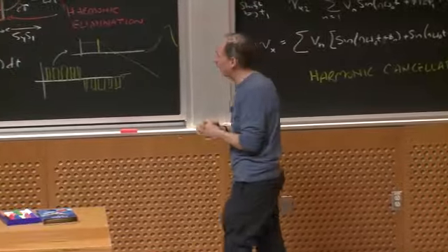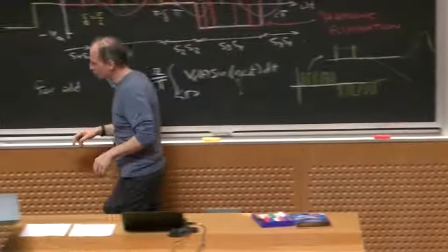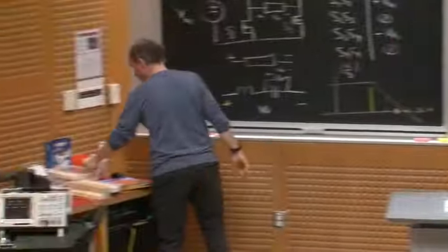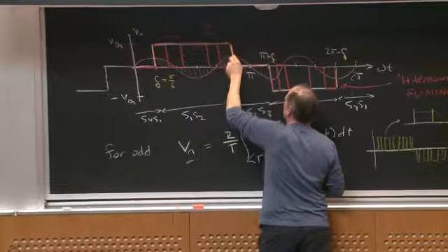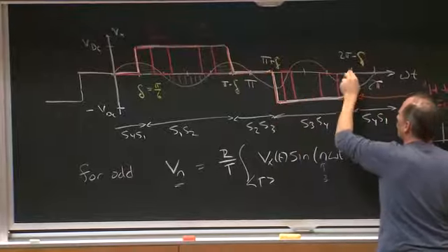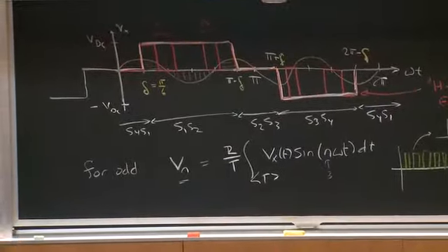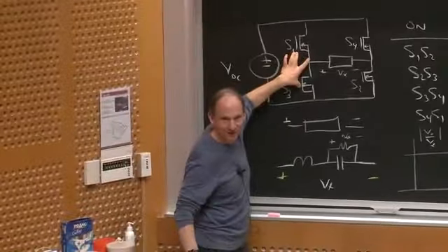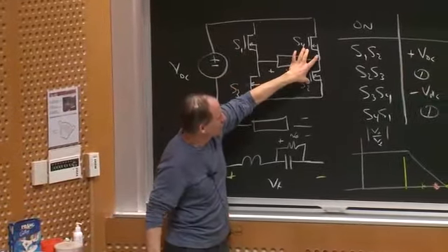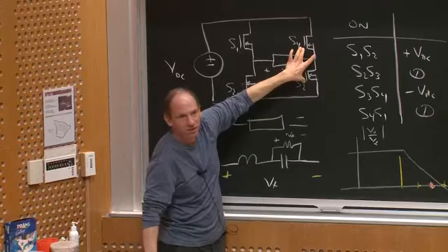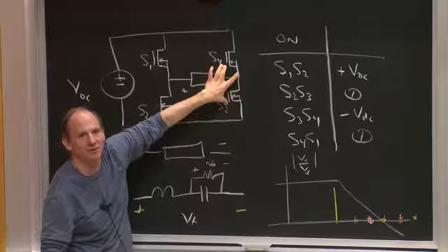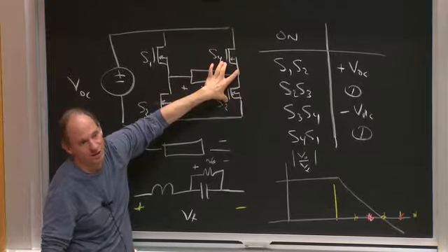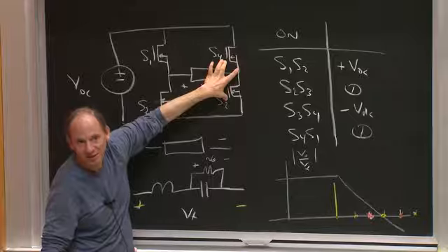And in fact, even if you come back to this original waveform that I drew, the original white waveform that had those 30-degree shifts, what I could really view that as is 1/2 of this bridge generating a square wave, and the other half of the bridge generating a square wave that's 60 degrees out of phase at the fundamental, and at 3 times the frequency, at the third harmonic, or 6th, 9th, 12th, etc., it'll be 180 degrees out of phase.